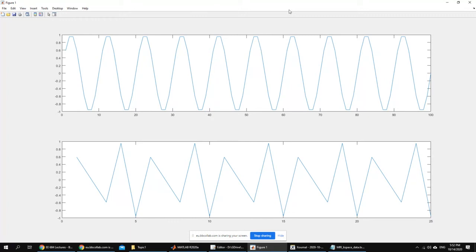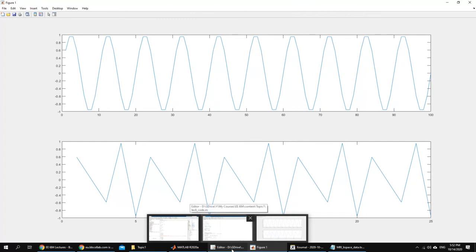So when you undersample, you can end up with something that doesn't look right. The other one, with 1 every 2 samples, looked a little bit distorted, doesn't look as good as the original, but it was okay. You can still see that it's a sinusoidal signal. Now you cannot determine that it's a sinusoidal signal from these samples.